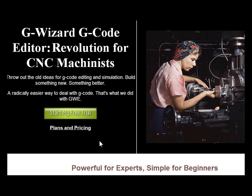Another reason to have a G-code editor is to modify your CAM-generated G-code. There's any number of ways to go in there and do things to the G-code that maybe are helpful to you. Maybe it's expensive to have your post updated to do some of these things. Maybe you need to have code changed to work on a machine with an earlier version of the control than what's on most of your machines.